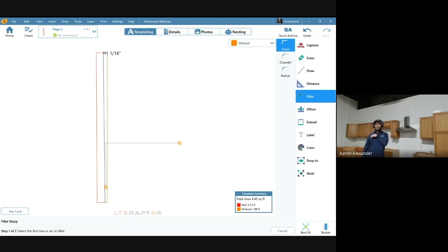Vince Strelo is one of our trainers there as well. He's in on this meeting, and he's saying there's 2 blocks per slab, right? So if we got 1 countertop here, we got 1 countertop on each side of our stove opening here per se. He's suggesting setting up 2 blocks on that to shoot the levelness and where that countertop is at in space, and then set your 2 blocks up here and shoot that countertop to see where that is in relation to the other ones, right? Then you have that information on your sheet right there, on your template. Right, good tip there, Vince. Thank you.